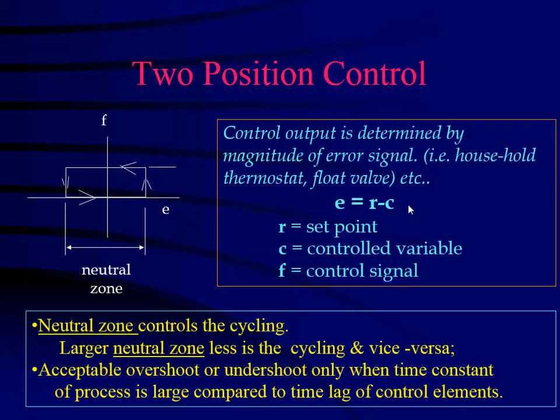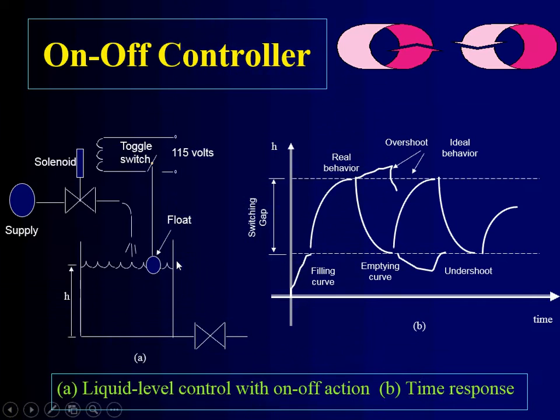So there's a liquid level controlling here, so you have a float in the air. As you can see, it has a supply of water, and this valve in here either opens or closes. Okay, so in here what will happen is when it fills up, you say disconnect this, so the valve is going to be, you know, the solenoid will act on this. But if this goes down, it closes the circuit, so it opens the valve and then lets the water in.